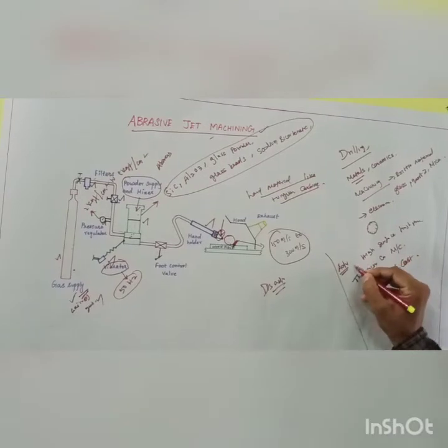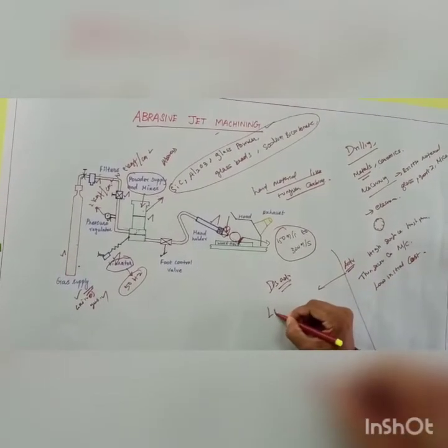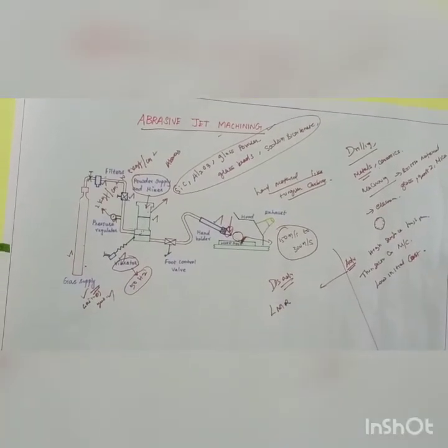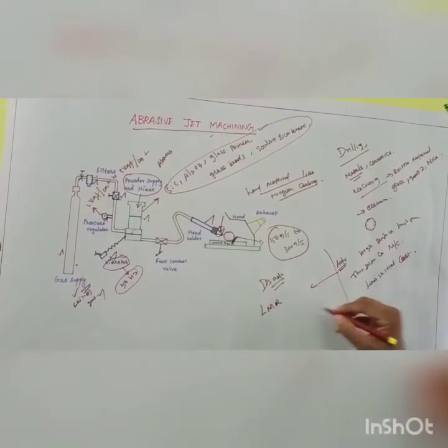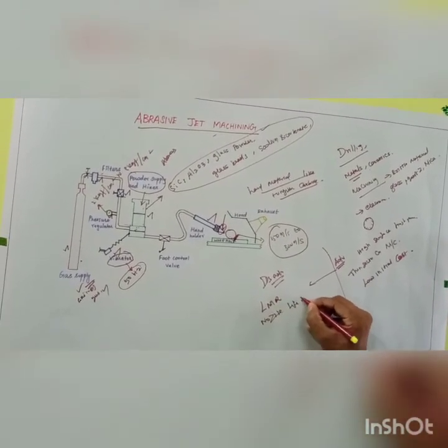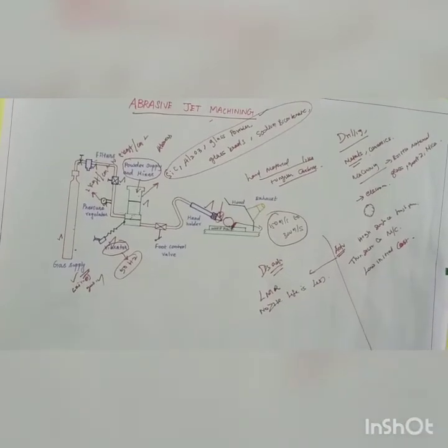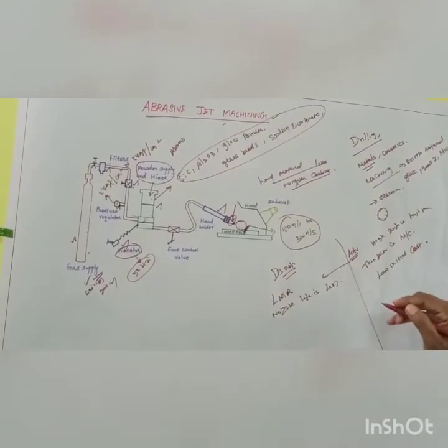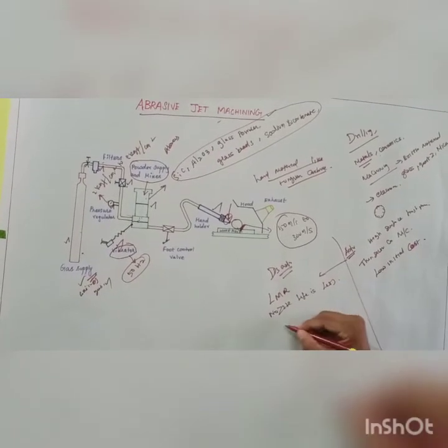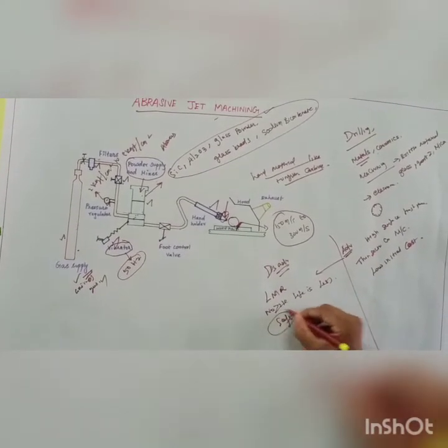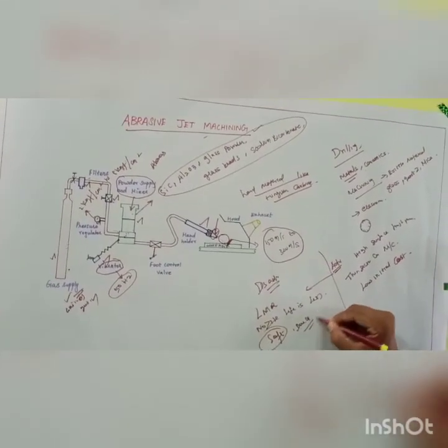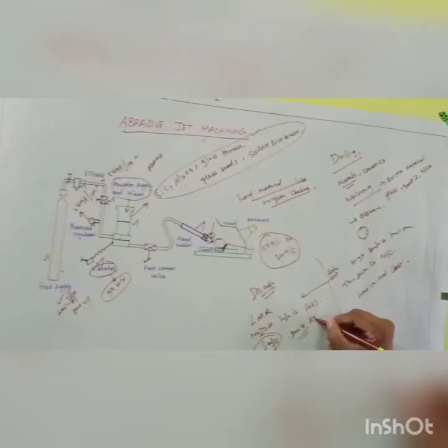Disadvantages are that a high surface finish means a low metal removal rate, and nozzle life is shortened. It is not used to machine soft and ductile materials. Soft materials and ductile materials cannot be machined using this abrasive jet machining process.